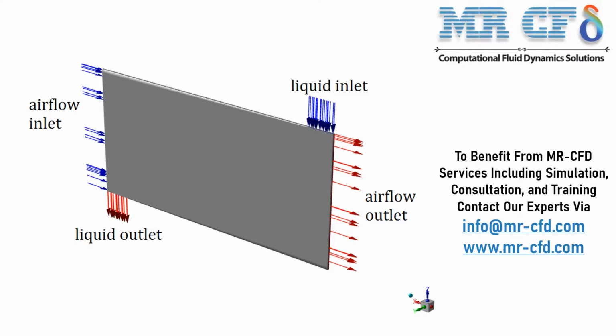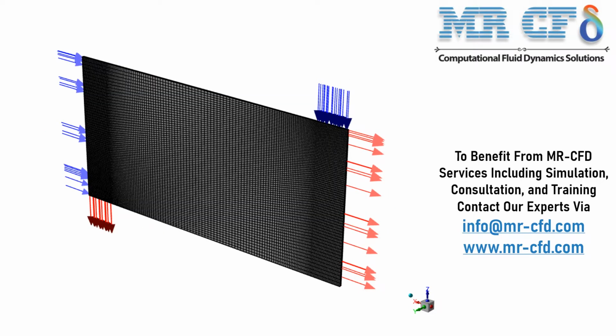The present model is a heat exchanger panel with two flow paths, such that on the one hand, the hot liquid flows and on the other hand, cool air flows in the opposite direction to the liquid flow. The outer walls also act as insulators. The meshing process of the present model is performed by ANSYS Meshing software. The mesh is unstructured and the element number is equal to 155,000. The cells are smaller and more accurate near the wall boundaries.